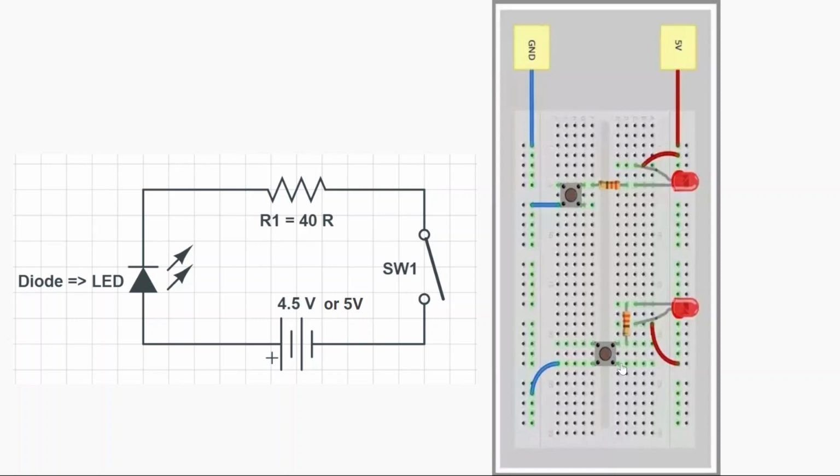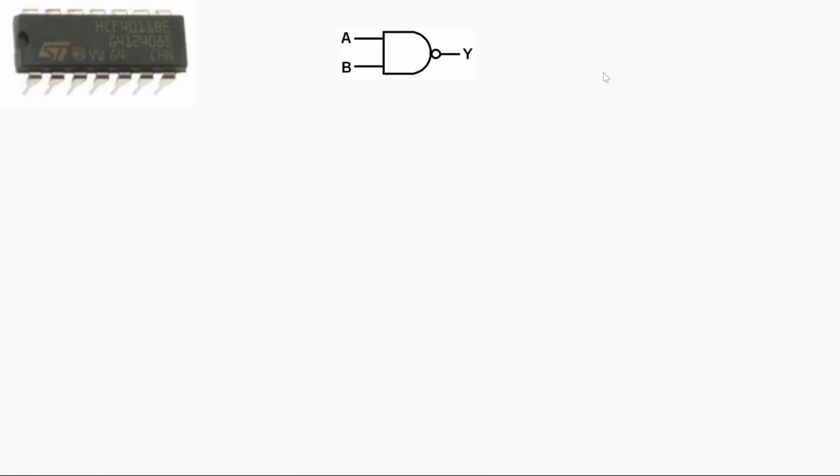1, 2, or 3, 4, doesn't matter, even though these are not connected, because once you press this button, all these lugs are connected, so it means this will connect here as well. And the negative side, one of the terminals of the switch, we are connecting to the negative power supply. Again, another configuration, and when you press the switch in this configuration as well, you will see the LED glow. So let's move to the next slide.